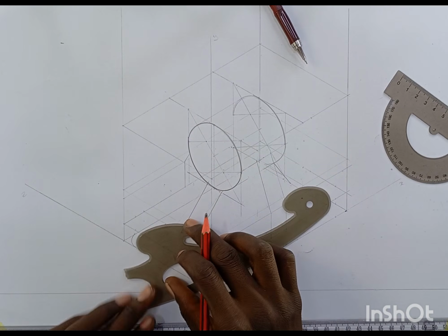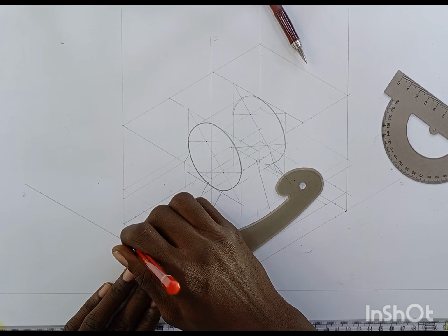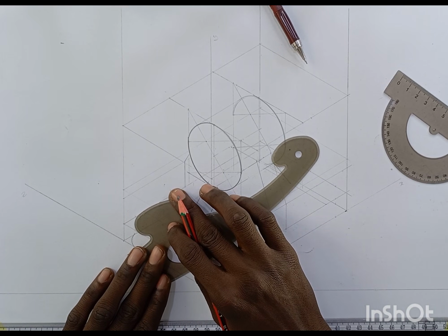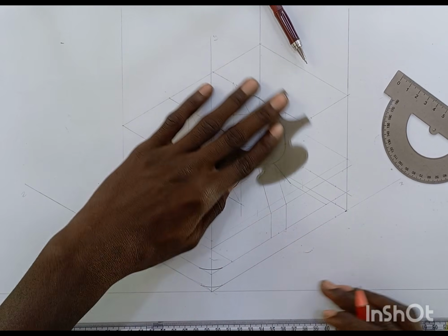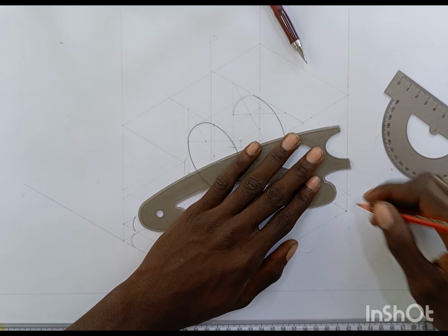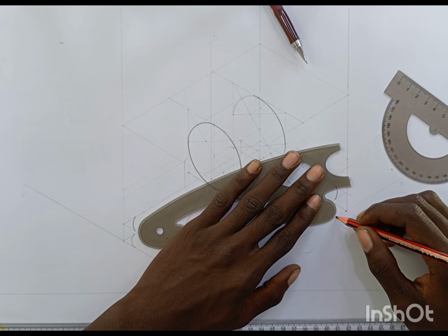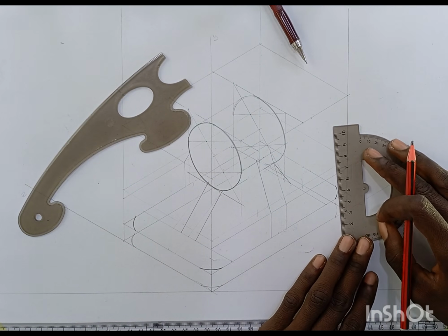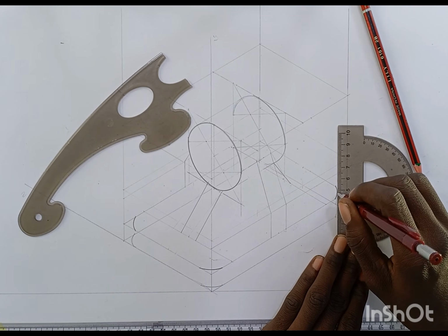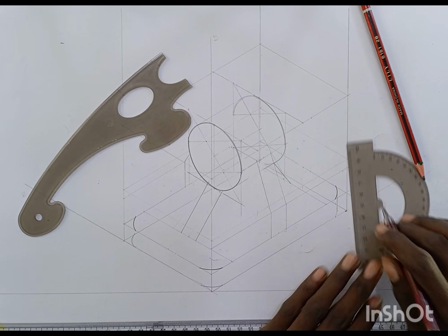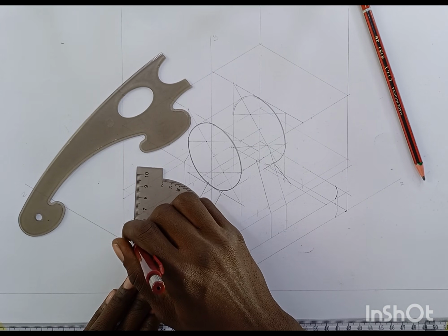And let's use this side. So here should be light, and here you can make it darker because it's going to be seen at the top. So now, same thing you're going to do here. You connect these 2 points here with the French curve. Then these 2 points you are going to connect with the French curve, a very light one. So now you are going to just what? With a straight line, you connect the points where they touch, like this. Okay. And this one also you are going to what? Connect the point where the 2 curves are tangential.